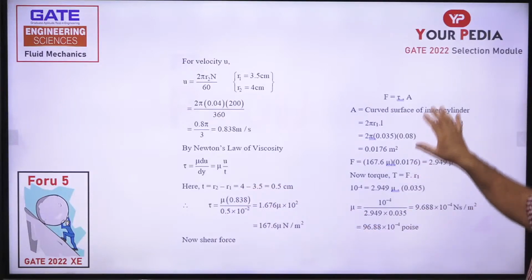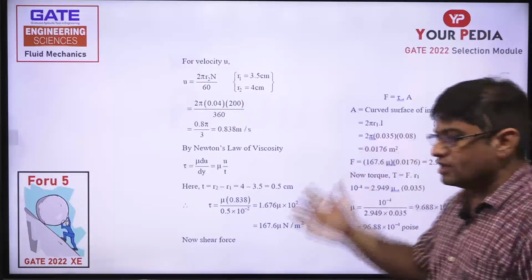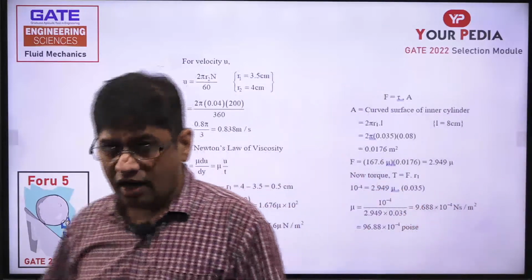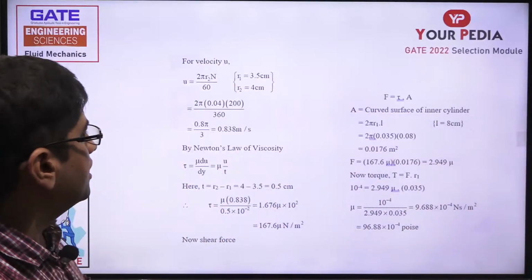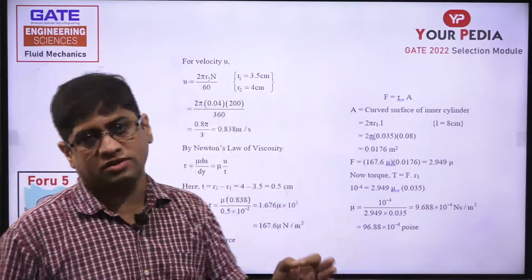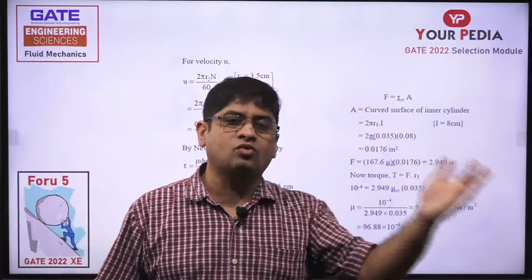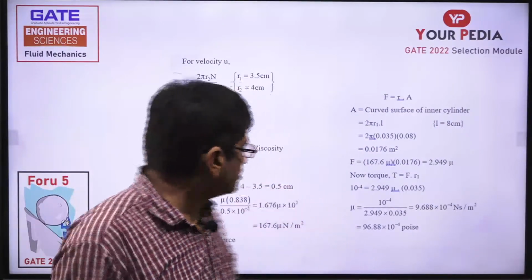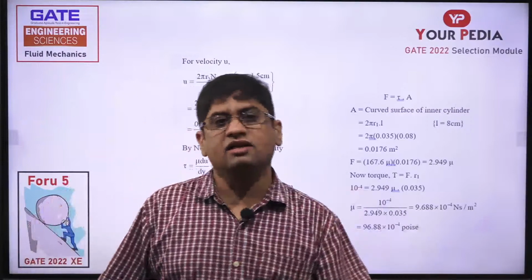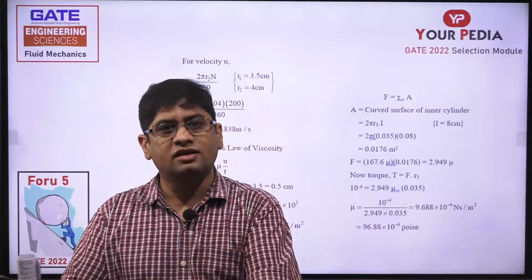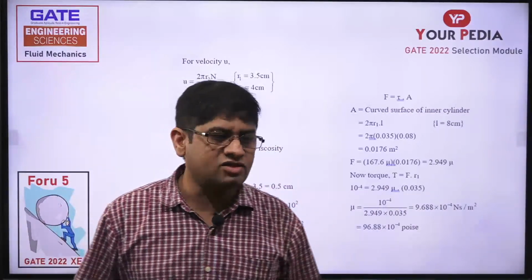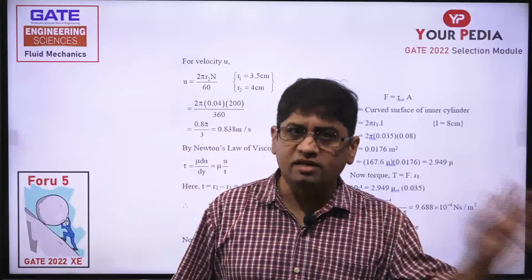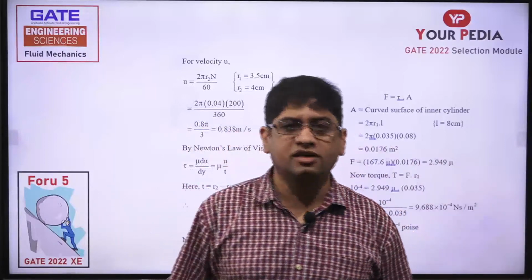Now that shear stress is helpful to give me the shear force. And remember that torque we are calculating at the inner cylinder. So the drag force is also to be calculated at the inner cylinder. Let me ask you one question. This shear stress tau is acting at the inner cylinder or outer cylinder or both? This shear stress is acting at both the inner cylinder and the outer cylinder also.